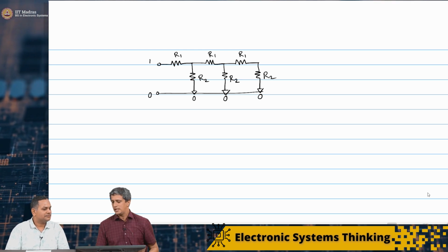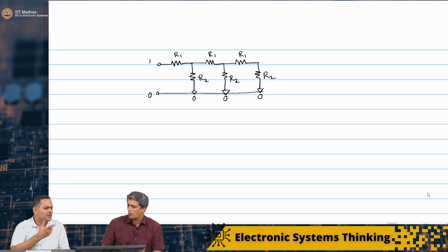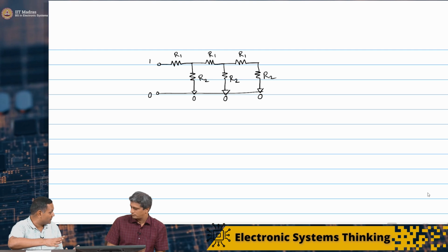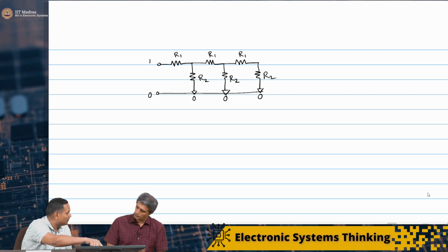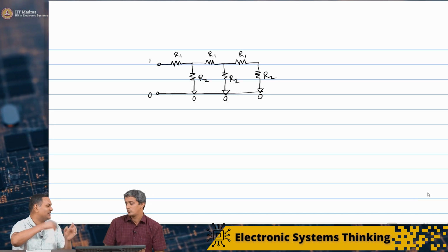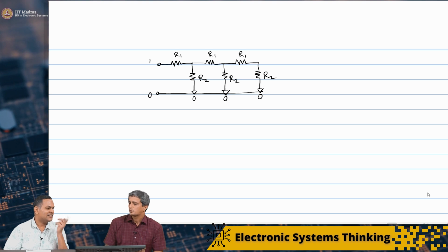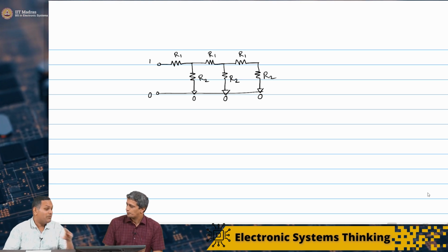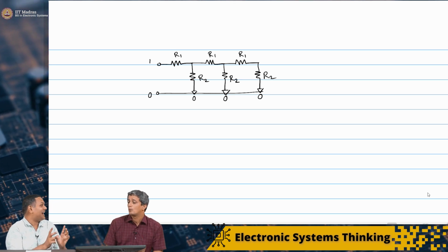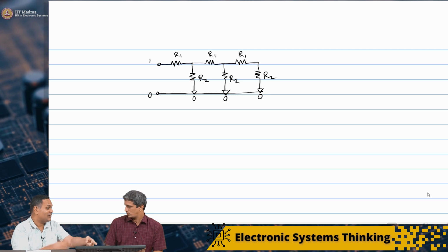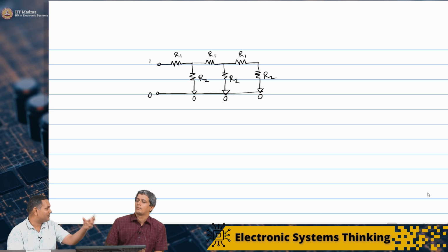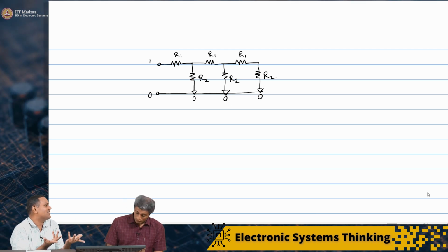So how would you solve this now? Of course, we could follow brute force. I see R1 and R2 in parallel, then in series, then in parallel with R2, and then I can do a bunch of combinations. But I suspect that there must be an easier way, because we have solved the previous question. Because we said we are adding one more section, the previous one is already hidden somewhere in here. Maybe we can use that to figure out what will happen by replacing that one with its equivalent resistance.